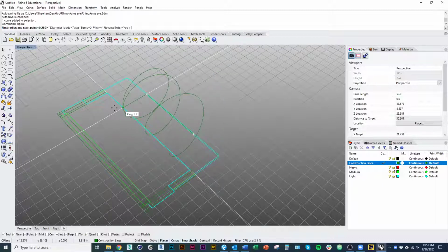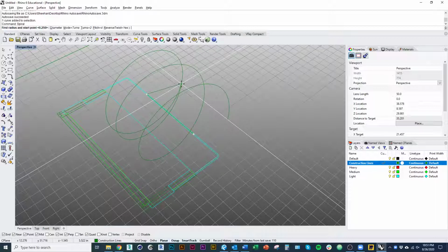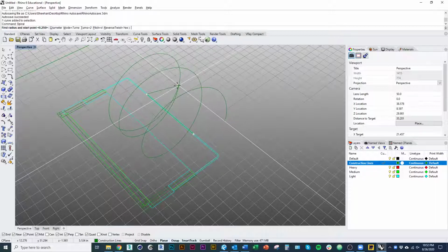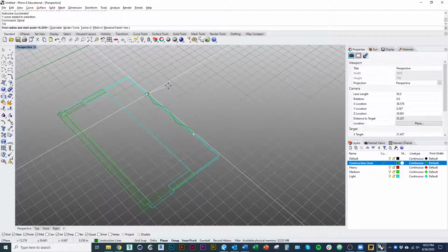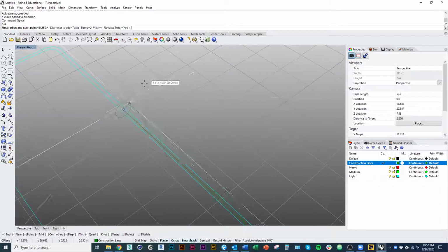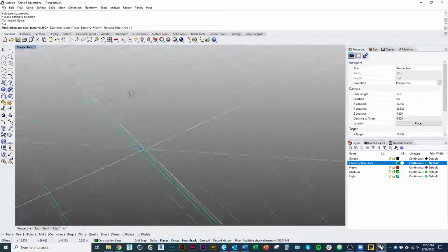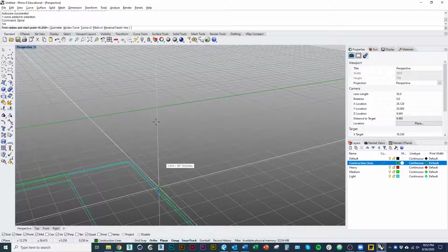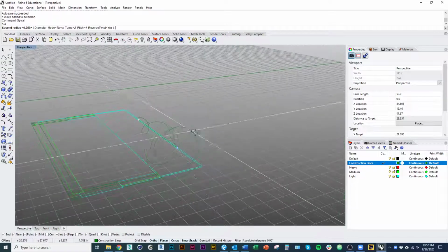The next thing that it'll need is radius. And because we know that the width of our flat bar is a 1/2 inch, the radius will be a 1/4 inch. 1 divided by 4. And then it'll want me to snap in a certain direction. And again, imagine we're drawing in plane with the width of our steel flat bar. I'm going to hold shift and draw that line straight up, vertical. And then I'll have to enter the same information on the other end.